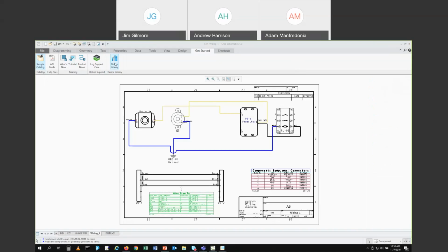You can go to pretty much any of the vendors that create connectors or components, and they will give you or be available to download step files or some type of data associated to that particular object. So if you want to populate the 3D catalog of information, then you would need to just add the attribute information and a coordinate system.